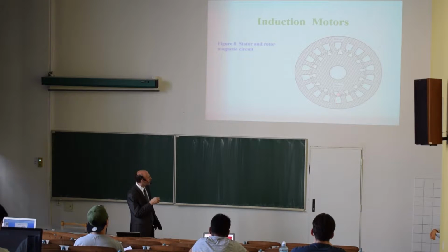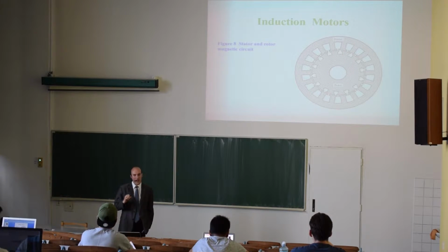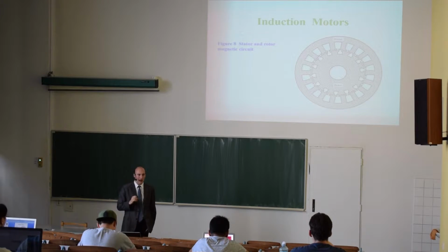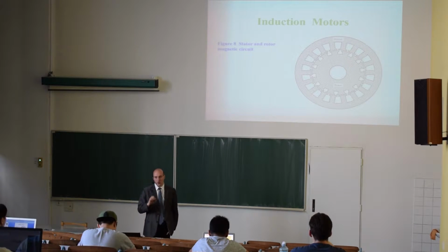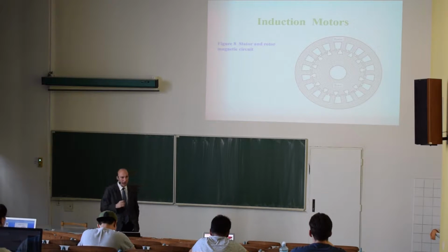The air gap here is the limiting factor. If you want to make a high torque machine, you need to make the air gap as small as possible. But on the other hand, if you make it too small, it may be very difficult to produce mechanically.